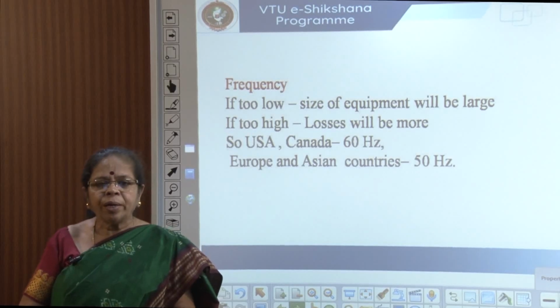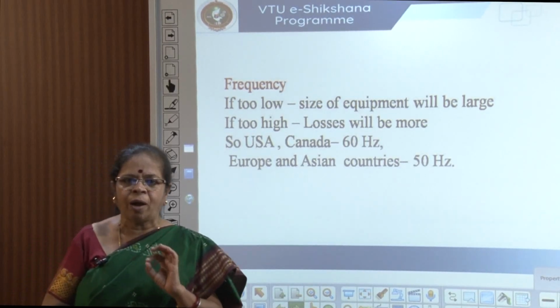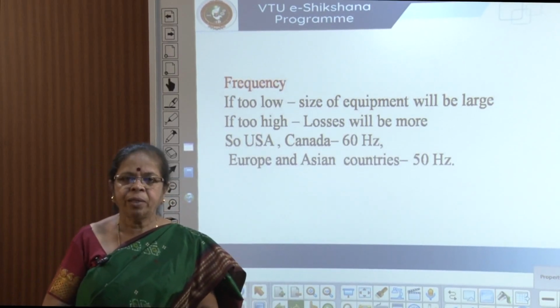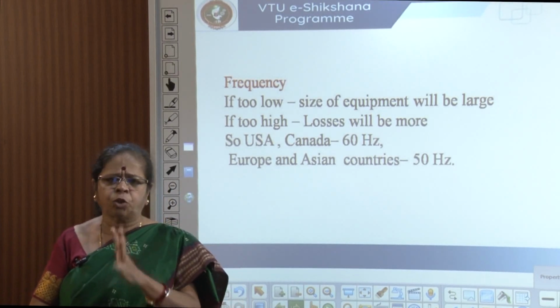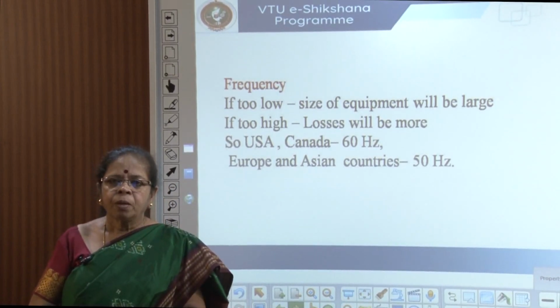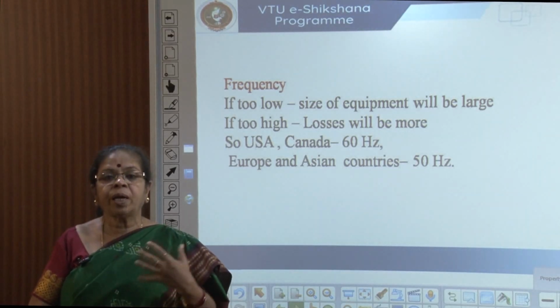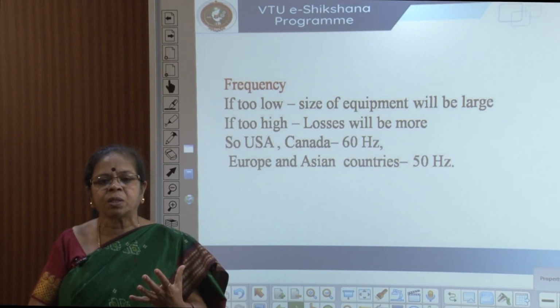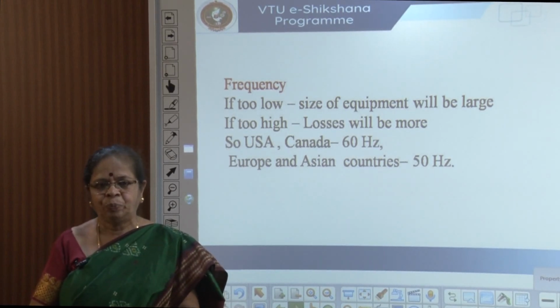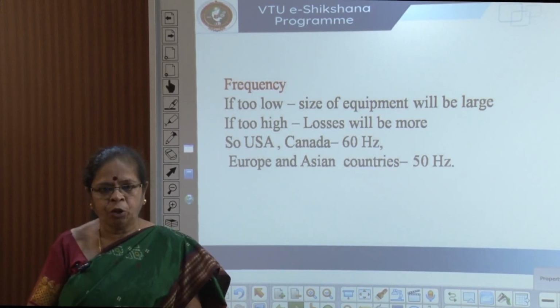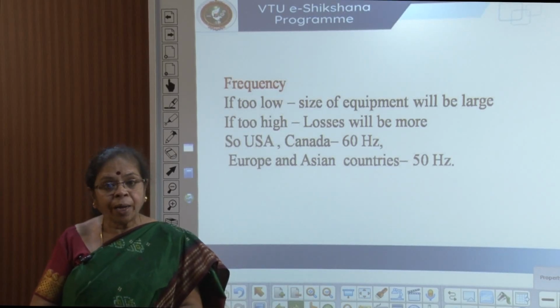So, people started wondering what is the best frequency to have for generation, transmission and distribution. If the frequency is too low, then for a given power, the size of your generators and motors will be very large. If it is too high, losses will be more.